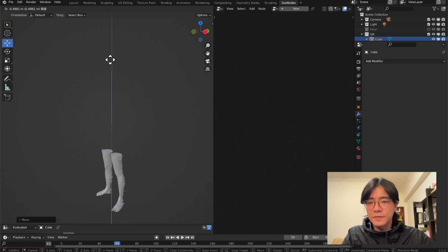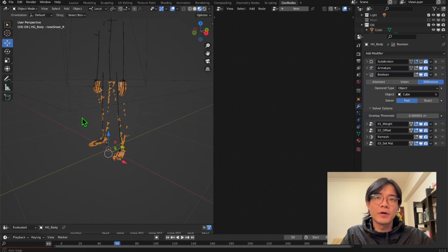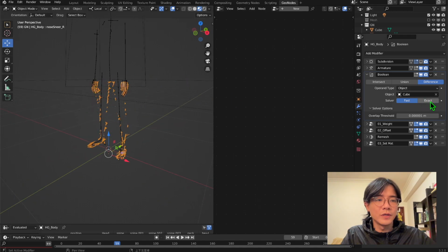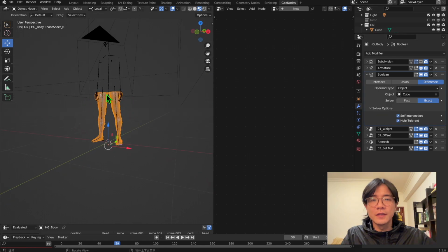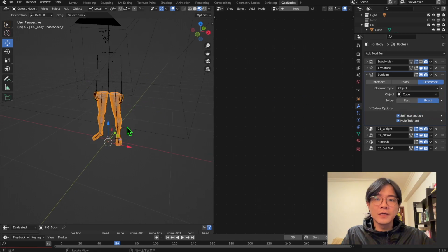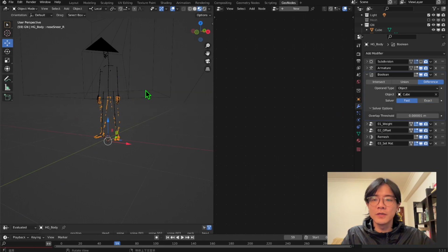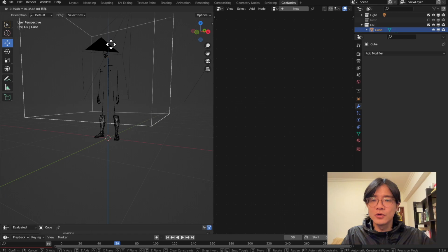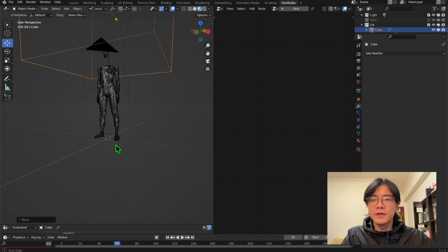You see here, sometimes you might find this bug, where it doesn't cut properly. In this case, you can switch to exact and make sure you have clicked both of these options. That will fix it, but it will be quite slow, so only use this when you are rendering. For testing, we use fast. We can ignore that for this moment. Keep dragging this cube. That's what we want. So we can leave it like this.